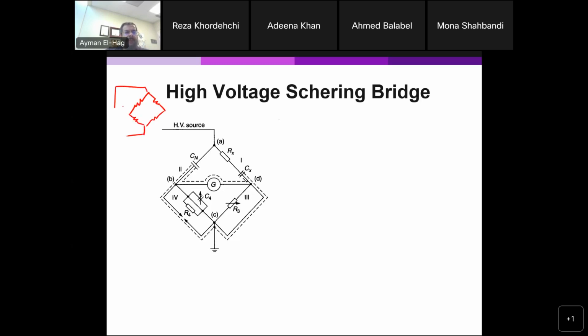So the bridge, for example, the Wheatstone bridge here, the same principle applies. You apply a voltage to it, let's say Vs. We have here R1, R2, R3, and R4, and you measure your V out. Now, if the bridge is balanced, your V out is equal to 0. Balance means R1 over R2 equal to R3 over R4.